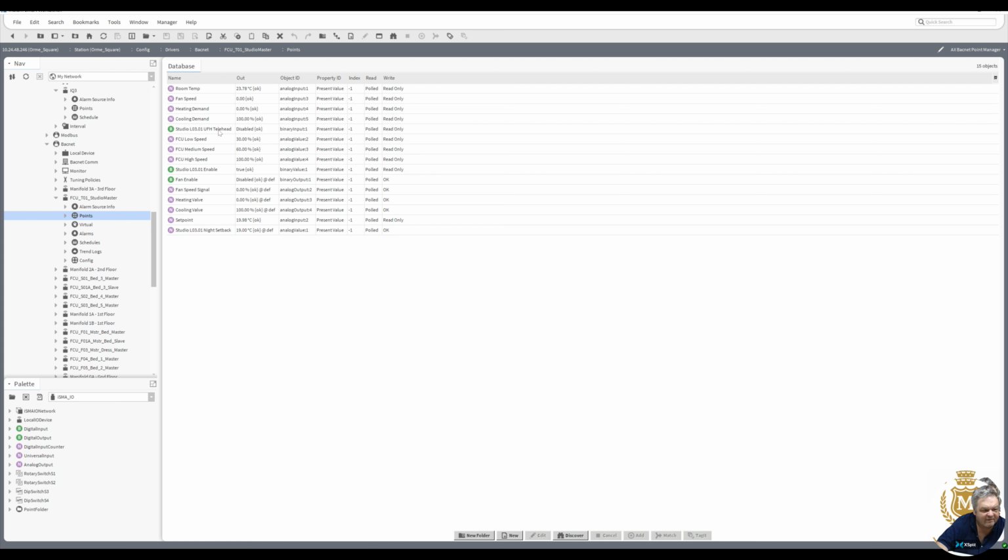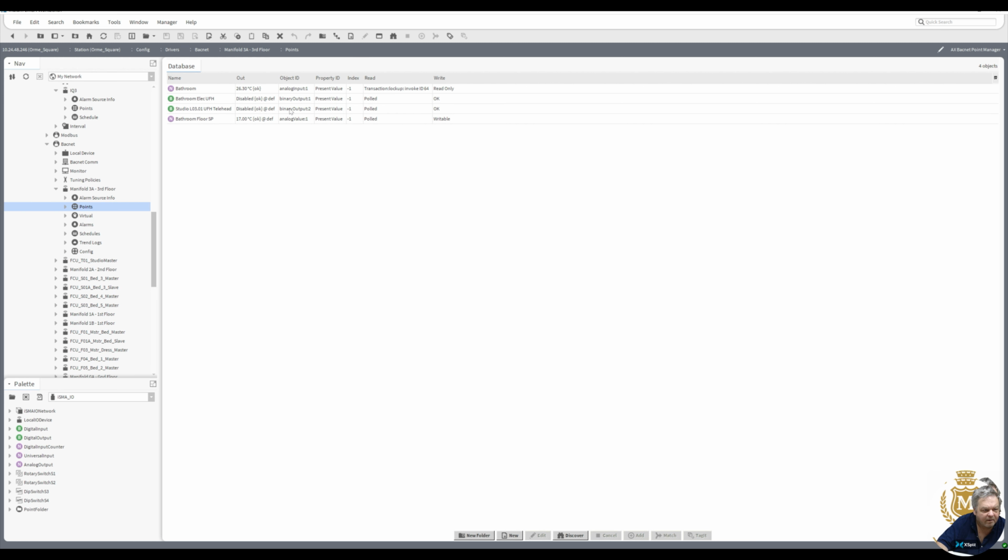Now that one is an underfloor head, so it's an underfloor heating head. It's actually fed by the geothermal heat pumps, because those heat pumps are set to around about 40 degrees, so it's great for underfloor heating. Look at a manifold. Temperature again. This is an electric underfloor heating. This is a water underfloor, so it's a valve underfloor heating. And the set point.